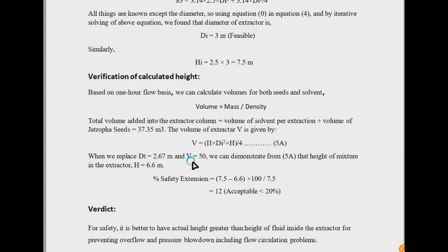concentrations, like here. The steady state function, as you see in reaction kinetics, is shown, but the k is not the reaction constant. The k is a mass transfer coefficient here, per minute, while oil concentrations are given in the liquid phase at time t in minutes, gram per liter.